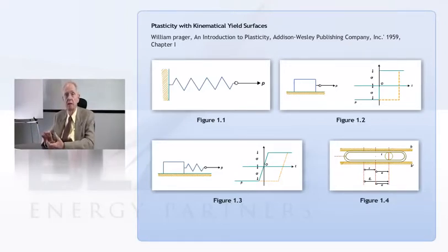Now, if I was imagining this material as being made up of a lot of little elements, like these sketches show, then they should have the property that if I were to make an array of them, so suppose I took one of these and stacked them next to each other and then put another stack up here and another stack up here, if I take that model and I go to find the stress-strain relations for that model, they should be the same, looking at stress and strain. They should be the same as the individual element.